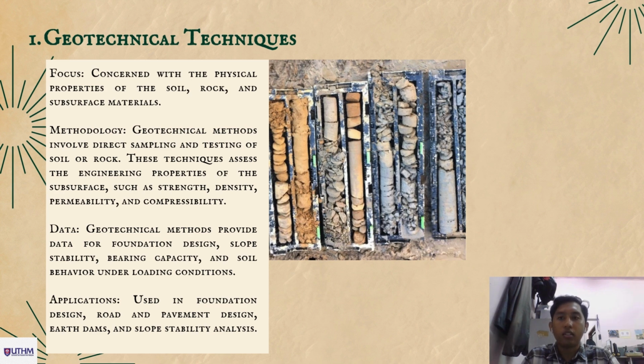These techniques assess the engineering properties of the subsurface, such as strength, density, permeability, and compressibility. For data, geotechnical techniques provide data for foundation design, slope stability, bearing capacity, and soil behavior under loading conditions. For application, geotechnical techniques are used in foundation design, road and pavement design, earth dams, and slope stability analysis.